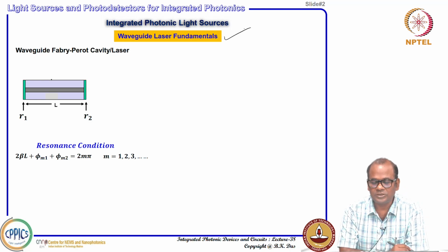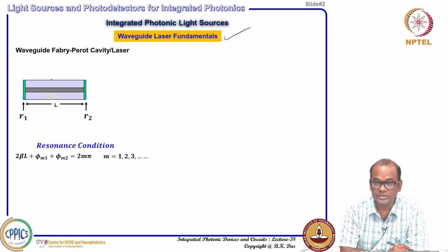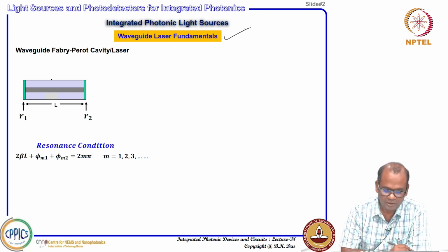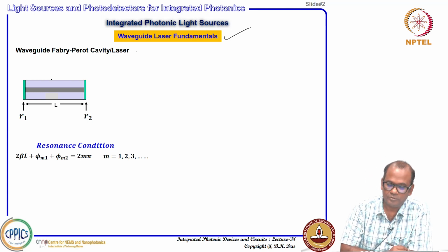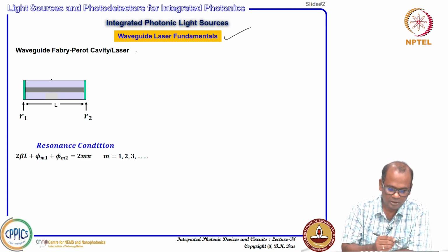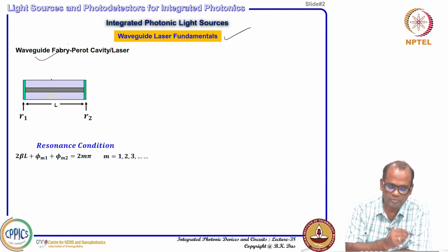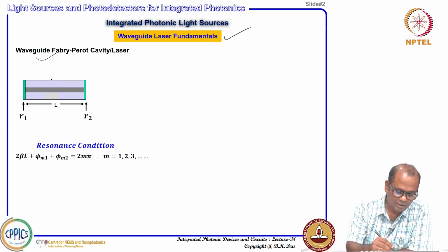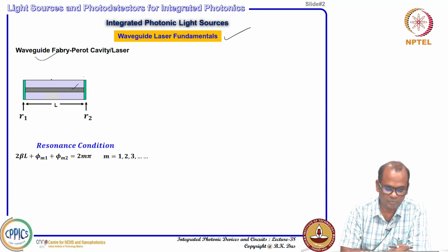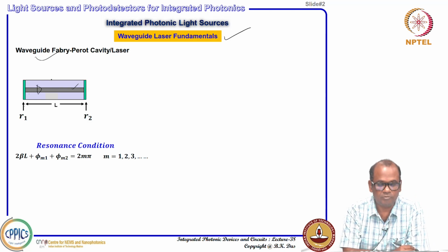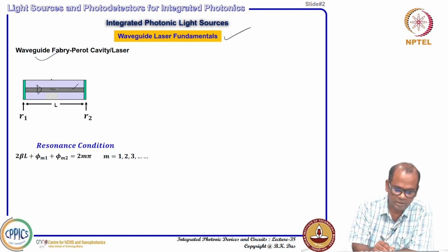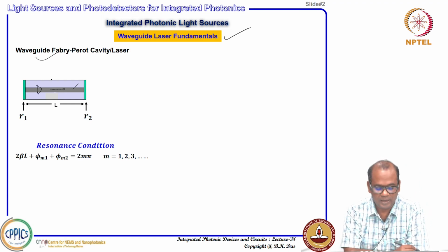It is not much different from laser fundamentals, the laser working principle. Just instead of a free running electromagnetic wave or light energy, we will be considering a guided mode, that is it. So, we start with a waveguide Fabry-Perot cavity. As shown here, this is the top view of the waveguide. It can be single mode, that means the field distribution will be confined laterally and vertically, but it is allowed to propagate in one direction.